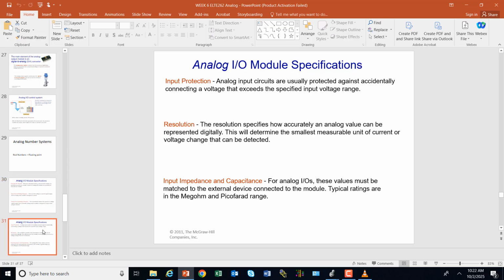There are some other things here, like input protection, and we talked about our resolution, and you can dive down into these analog modules and the thermocouple modules, and we will a little bit as we start getting a few problems. Now, I'll tell you a problem right now is that they're not fully calibrated, so we're going 0 to 10 volts, but the trainer is not producing all the way up to 10 volts.